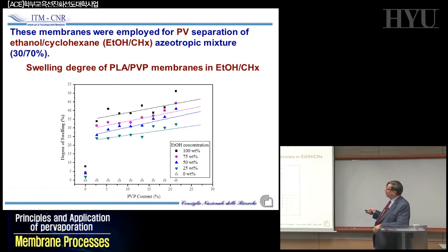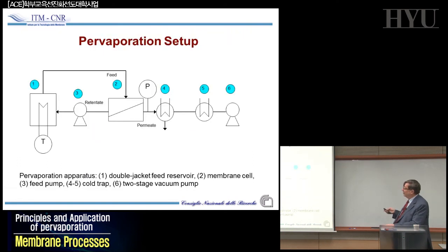So one of these problems is always to measure the swelling of your materials in the solution in which you are working. And depending on whether you have to do something more, like cross-linking, you saw the PVA membranes; they are commercial, but they are cross-linked membranes. If there were no cross-linking, this membrane would not exist. And that will be just the measure of the degree of swelling. So this is one of the measures you always have to do before deciding if the system is working or not.